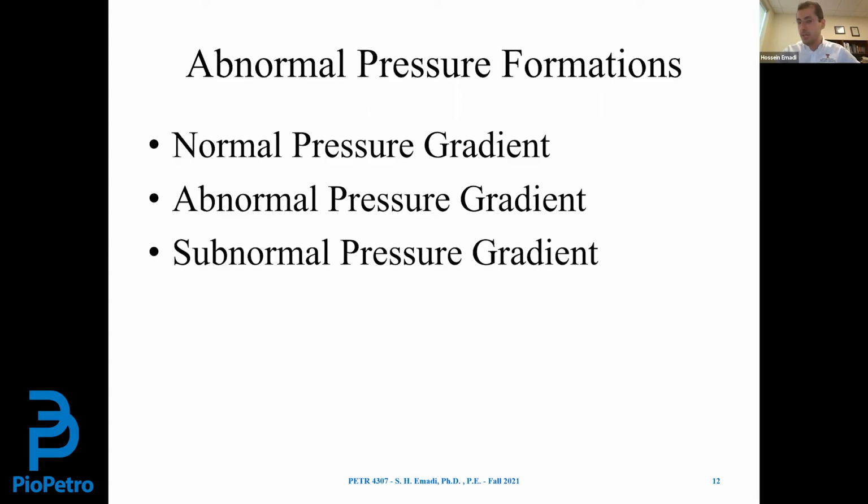Now the pressure at that point will be 550 psi instead of 465. Imagine your anticipation is that bottom pressure should be equal to 465 psi. However, in reality, the bottom pressure is 550 psi. And if this happens, obviously you're going underbalanced and formation fluid can simply enter the wellbore, causing a kick, and then possibly a blowout. Does that make sense? So it's very important to basically recognize